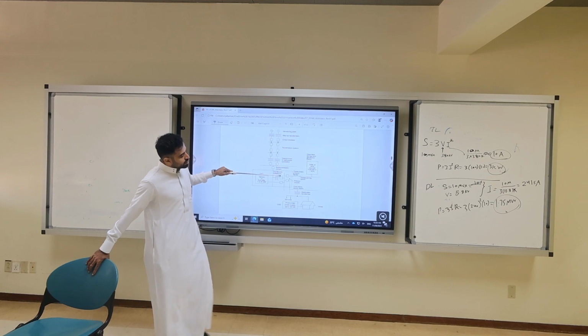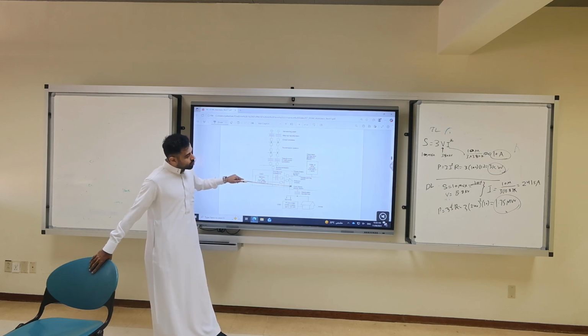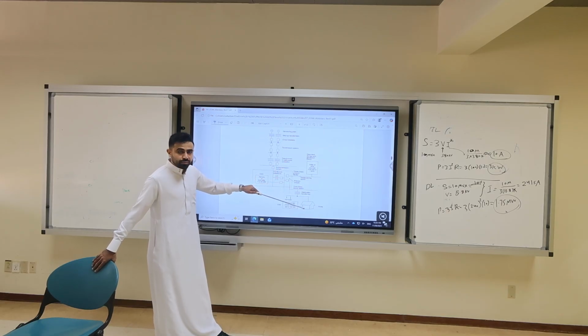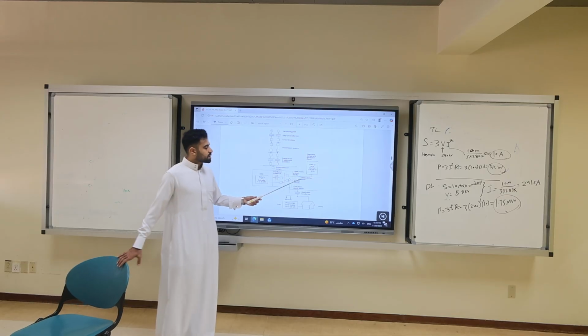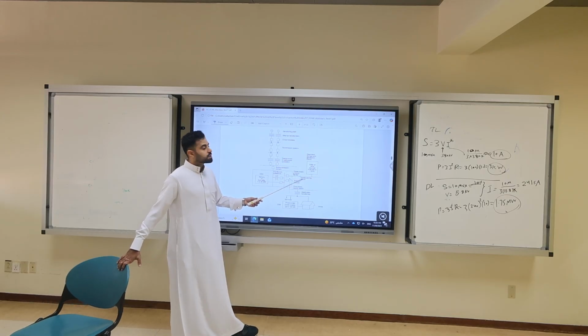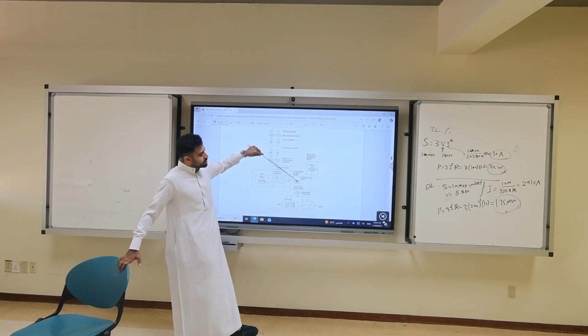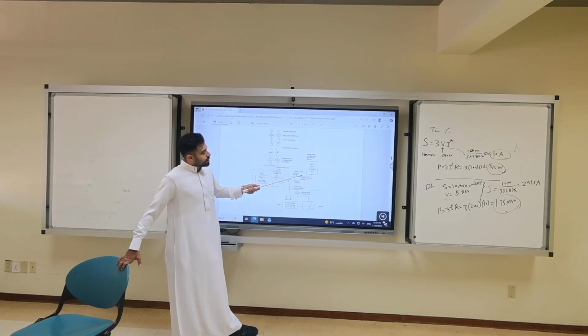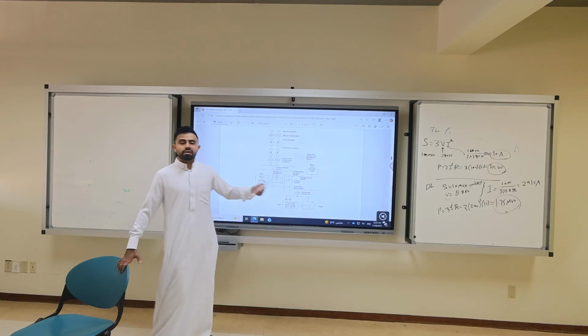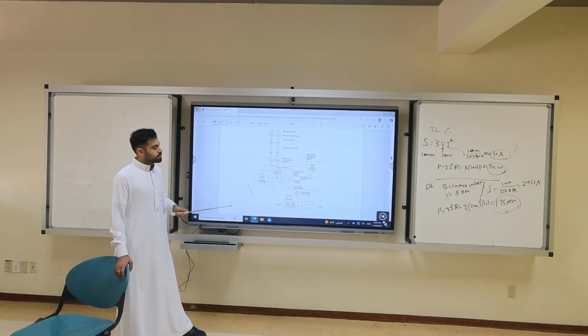Then here we have a feeder, maybe one phase feeder with a single phase transformer to the home, and it may have solar cell, maybe other services, or a three-phase feeder where we have a sectionalizing switch, from section, every feeder. It can also be supplied with solar or wind, and then they go to three-phase to other feeders. This is the general structure of the distribution.